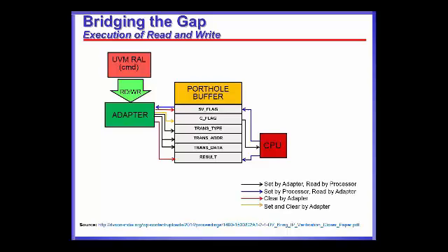And then we created two flags. One to indicate that there is a transaction that has come from the UVM or SystemVerilog side, and the other one is from the CPU. So we call it the SV flag and the C flag. And then we created one memory location to write the results also.